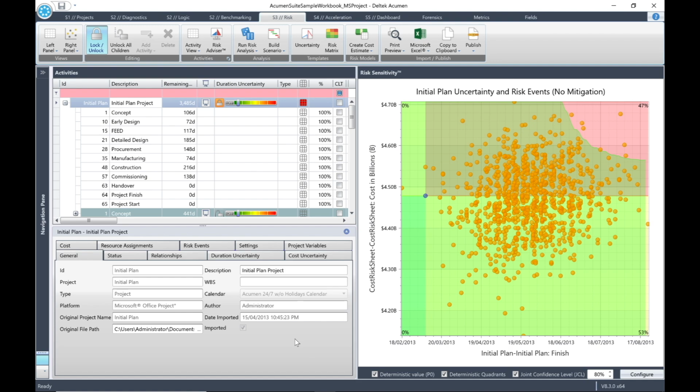So, instead of looking at the critical path at activity level, you can run simulations for the entire project. Each time a simulation is run, Acumen Risk takes note of the critical path for that simulation. Then, as you run more and more simulations, you'll find that some of the paths get repeated. It is those most common critical paths that you would want to see.